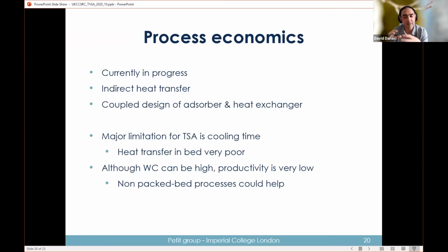In the case of steam regeneration, there aren't too many studies available yet to show that that is a good idea. Most of the computational studies assume that the steam does not condense and does not fill the pores. But that is yet to be demonstrated. I know that a few DAC companies are employing steam regeneration, but what impacts that has on the adsorbent and on the mass transfer is yet to be established.